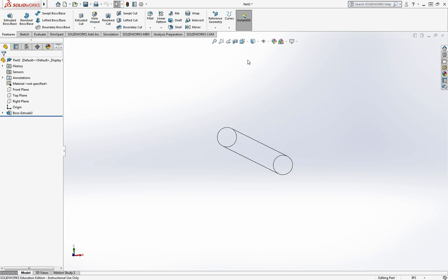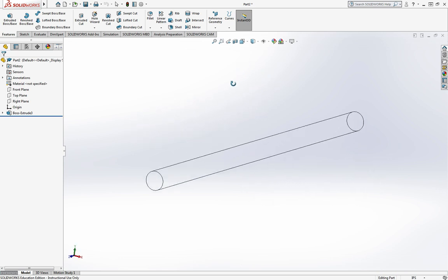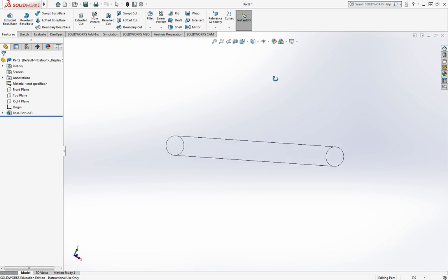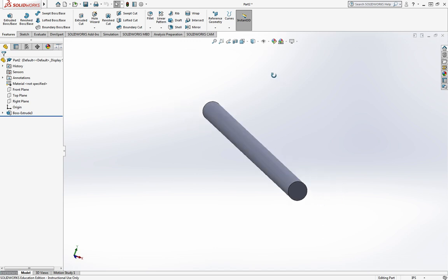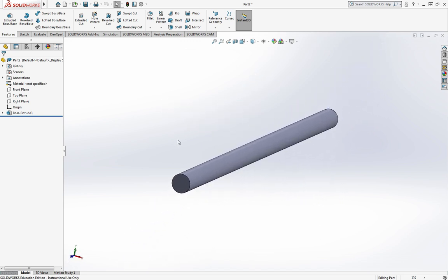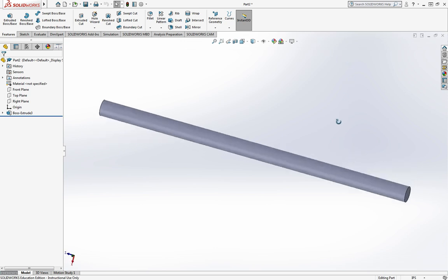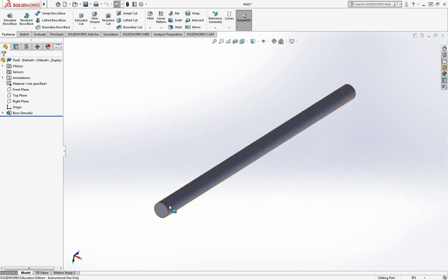And you can also change it to wireframe so that even the hidden lines are shown, and I'm not a big fan of this one. I don't really ever use it. I'm sure there's an application, but it's not one for me. So I like to be in this view here. That's just more of a visual representation of what the part looks like for me, and it also displays the lines. Then I know exactly where shapes start and stop. Alright, cool. So that's how you do that. Alright, go ahead and pause the video and practice that. Then we'll draw a cube.